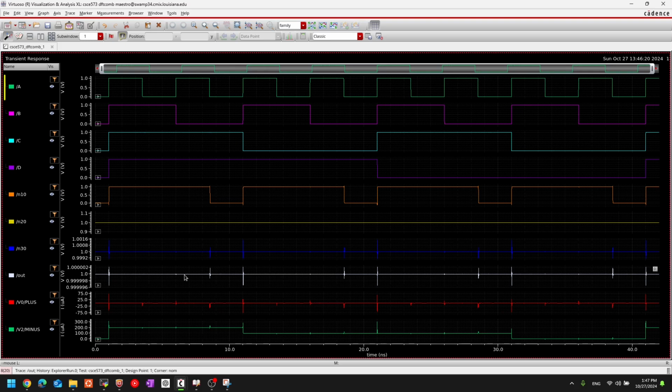But here's the thing. In reality, you don't have access to the intermediate nodes. So in reality, you have faults almost everywhere in the circuit, depending on the manufacturing process. You could have a fault at N20 and your circuit stops working and it's literally not functionally correct.